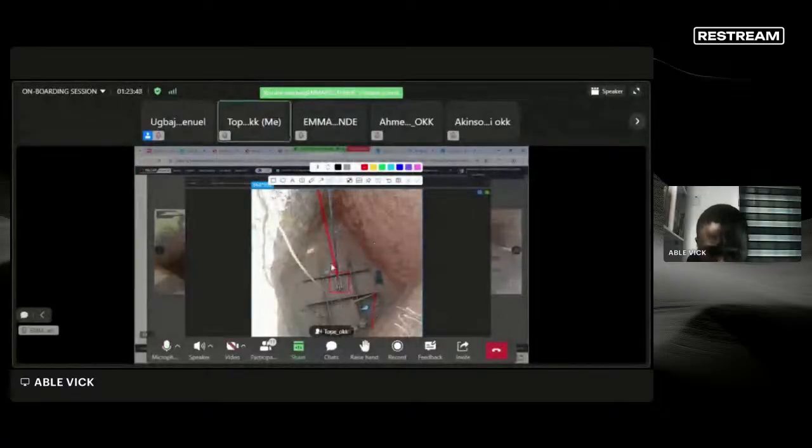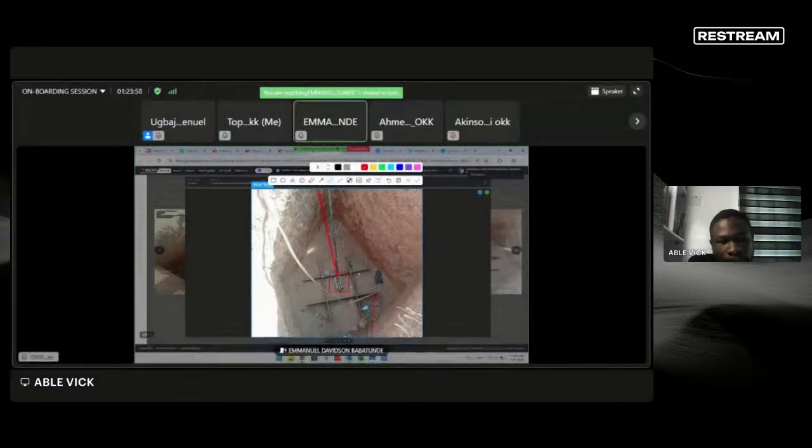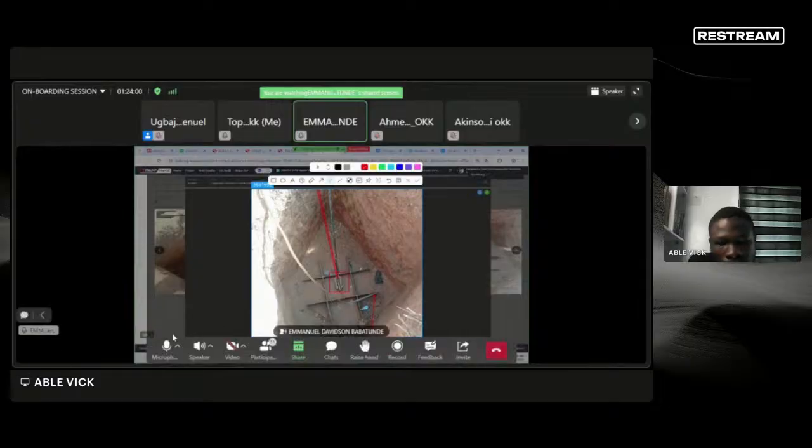That's what I'm saying. The base plate should have been rotated. You need to rotate it a bit. Yes, that's the correction that this person should have done. Maybe he did it before he backfilled. Nobody can tell. But from this picture, this base plate needed a little rotation to make it aligned.